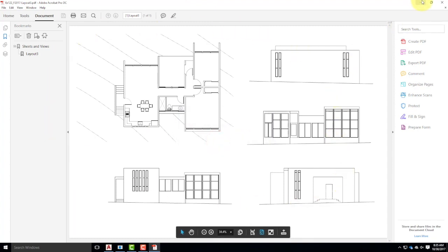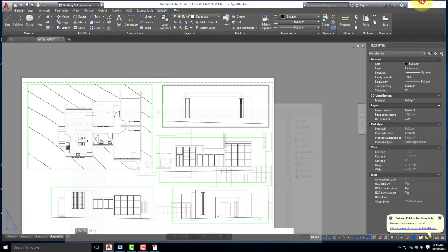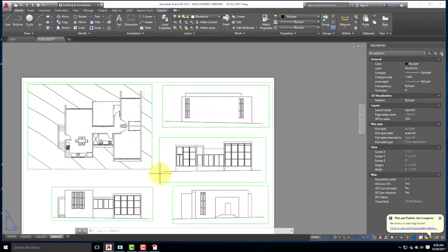If I were doing a pure AutoCAD drawing, Paperspace is also the place that I'd put text and symbols and dimensions and leaders and all of that sort of thing. We're not going to do that in this class. We will probably put a little bit of text in Illustrator afterward, and I'll show you kind of graphically what you might want to do. But for the most part, we're going to stay away from text and we're going to stay away from dimensions. If you need to put dimensions in a drawing, though, this is the place that you would be doing it. And AutoCAD is really good at doing it, but you'd be doing it in Paperspace, not in Modelspace.